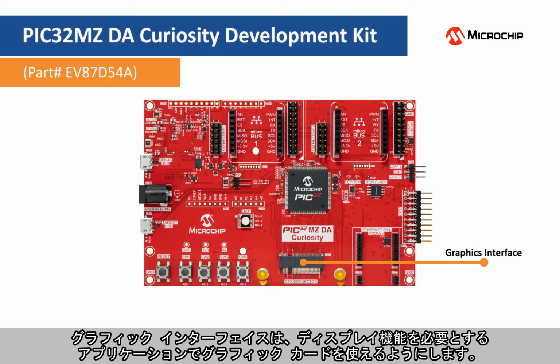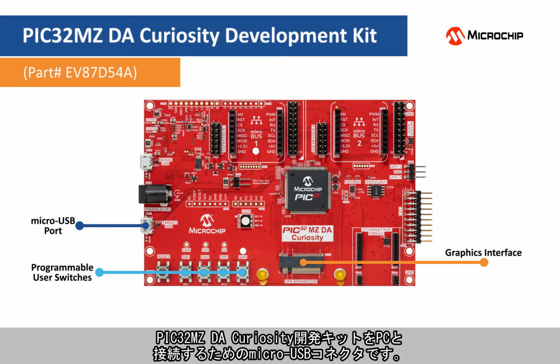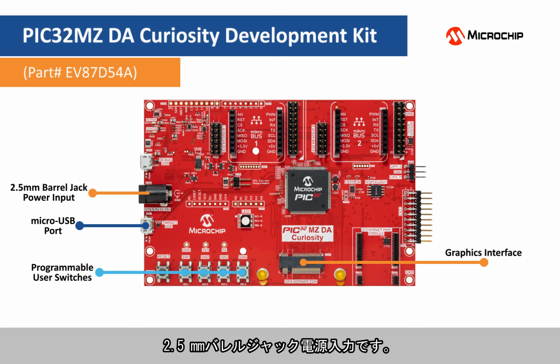This EEPROM has a factory-programmed EUI-48 or EUI-64 address, plus an embedded unique serial number. The graphics interface enables the use of graphics cards for applications requiring display capability. There are 4 user switches, helpful in reading user inputs. A micro USB connector to connect the PIC32MZ DA Curiosity Development Kit with a PC. A 2.5mm barrel jack power input.